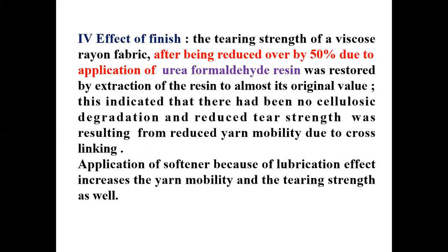And we have studied that the tearing strength in general will depend on two things. First of all, it depends on the tensile strength of the yarn, and secondly, how free it is. Okay, higher the degree of freedom, more will be the tearing strength, because more and more yarn can form the group together and they can resist the tearing force better.